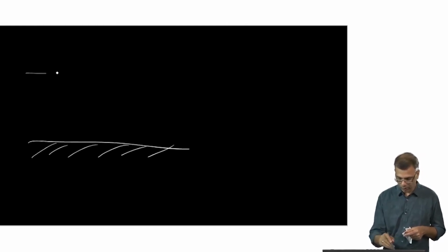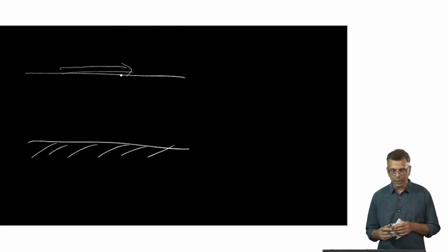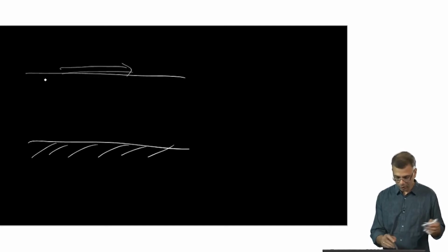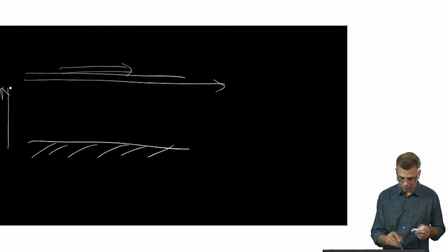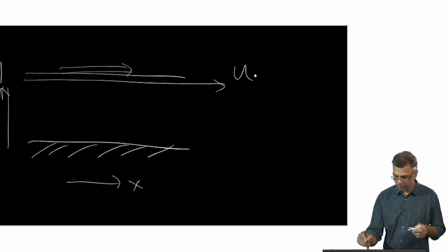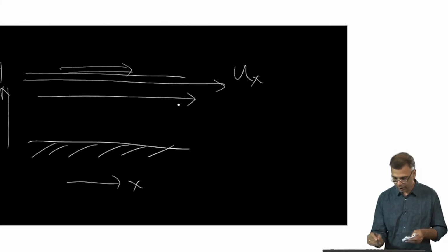And more specifically, in the same kind of situation, you have a fluid surface like this, and you apply some kind of force, say wind blowing over the surface of a lake. Suppose this was a container filled with honey. If you apply a force on the top surface, you can think of the top surface flowing with some kind of velocity. Suppose this was the y coordinate and this is the x coordinate, and you have an x-directed velocity like that. The top surface would flow fastest, and the next layer would flow, but not nearly as fast, with a slightly reduced velocity.